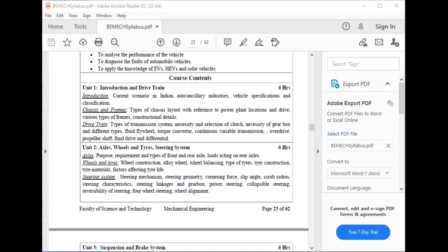If we see the components in this pressure plate: the cover, then the pressure spring, then the roller is provided. This is the pressure plate, then pins, eye bolt, release lever, and a strut is provided here. Then for checking this pressure plate, if we pass a circular rod on this pressure plate, we are able to find out the warpage, if any is present.